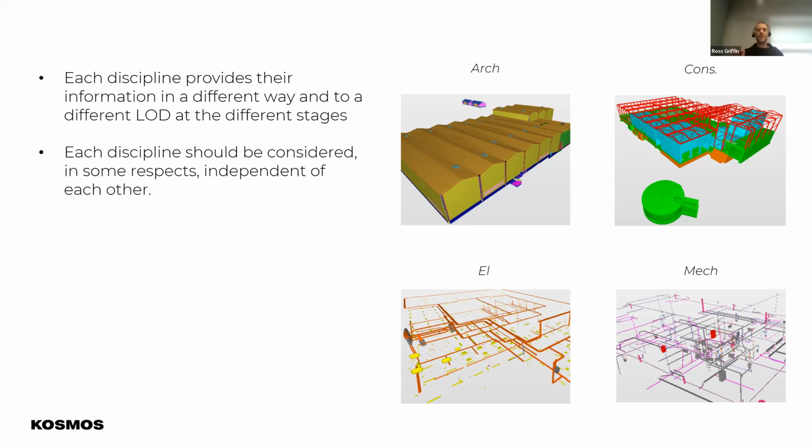But at this stage, we will know the different unfederated models. And as we mentioned, it can be 5 up depending on the type of project. In these early stages, what we're trying to do is take as much information as possible from the models, because we're starting that project life cycle of cost estimating and bill of quantity production quite early.